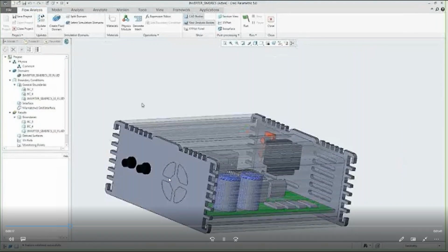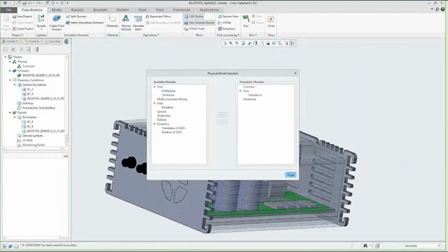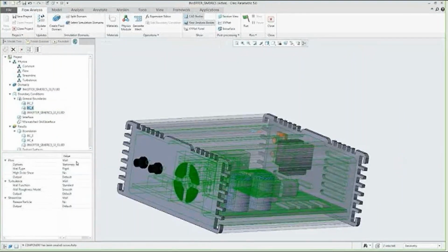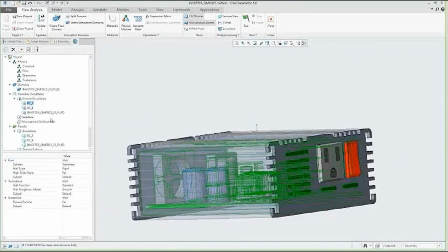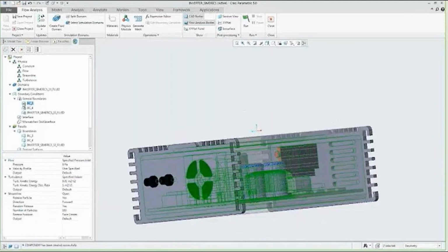The nice thing about it, so watch this, it does surface and bounds. So you work directly on the geometry. Here I'm picking that surface of this thing and it closes it off right there. So once we close off everything, then it can figure out what the volume is that's going to be our fluid, and it knows where the solid stuff is. So we don't have to go into any weird mode or do any translations. It works directly on the geometry, solves really, really fast, and figures out what the volume is, and then we say, okay, this volume is air, or it's a liquid, and it has this temperature, and it's flowing this fast. So it starts to do that type of analysis, and like I said, it solves really, really quickly.